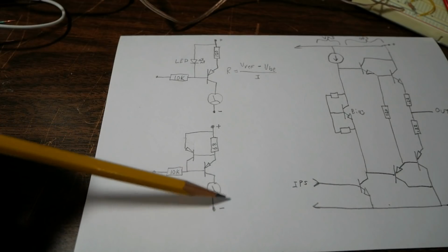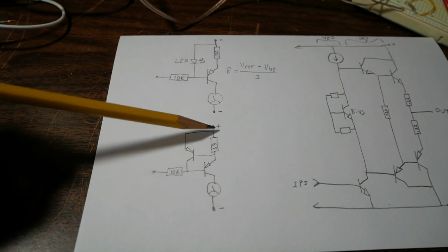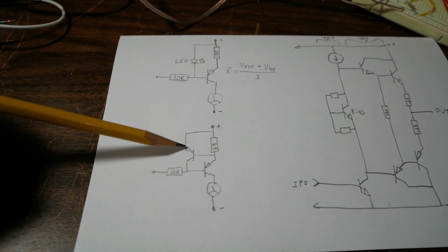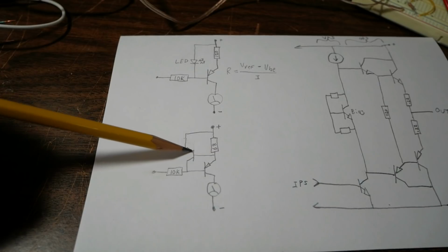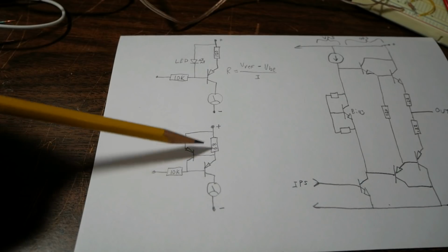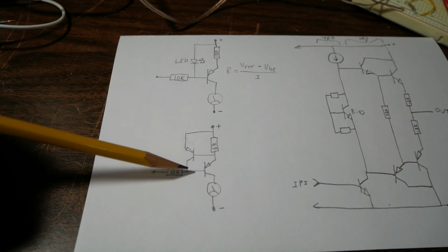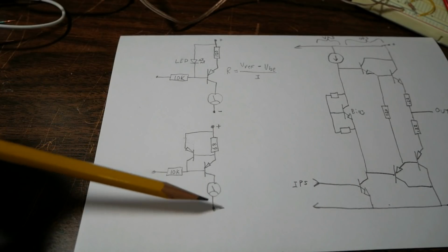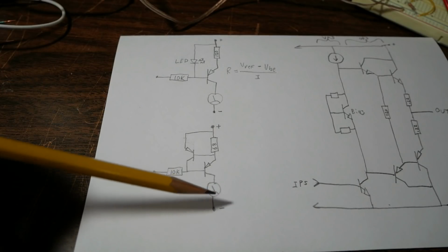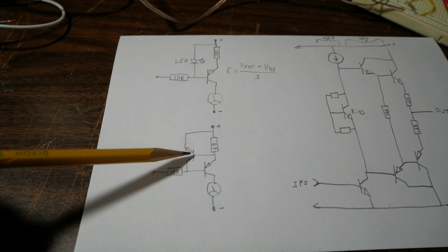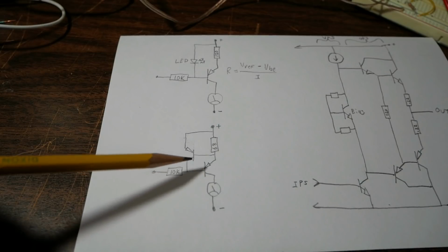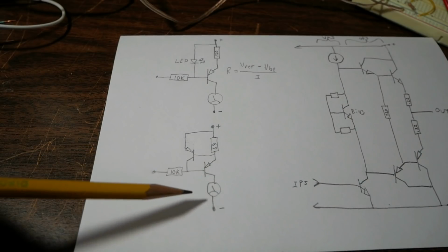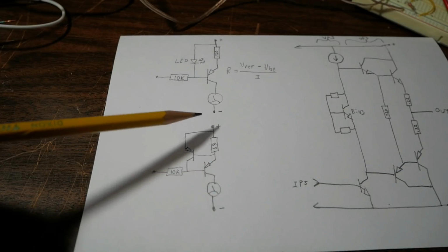And of course, with less voltage drop, a smaller voltage drop here decreases the current, turning this transistor on less, so it shunts less current. More current's going to go this way, and turn this transistor on more to bring the current back up. But with this transistor being an active device, it should be more precise in its operation due to the effects of feedback.